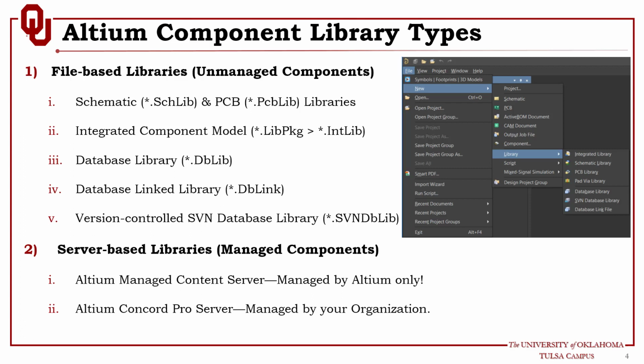For instance, my own integrated library that holds thousands of components is located on my company OneDrive. So if I am using my personal computer at home, I can point to it. If I'm at the company in the office, I can point to it. Wherever I am, I can point to it and use it at any time. And this is the most commonly used library among all PCB designers, I mean, the file-based library.